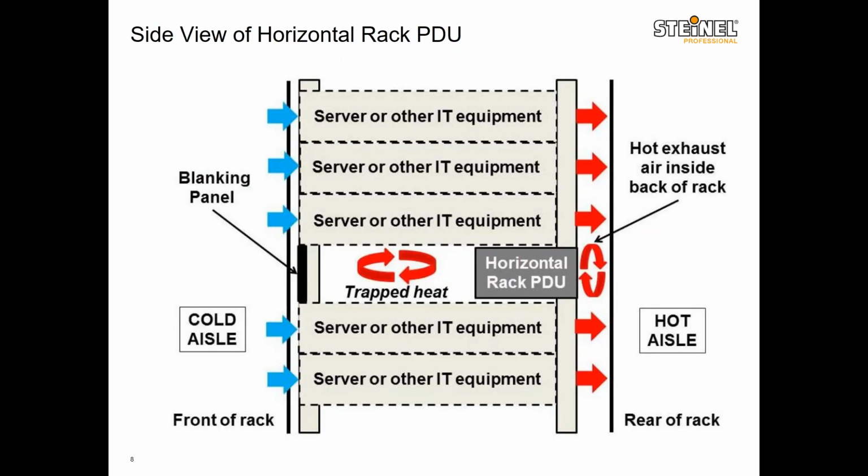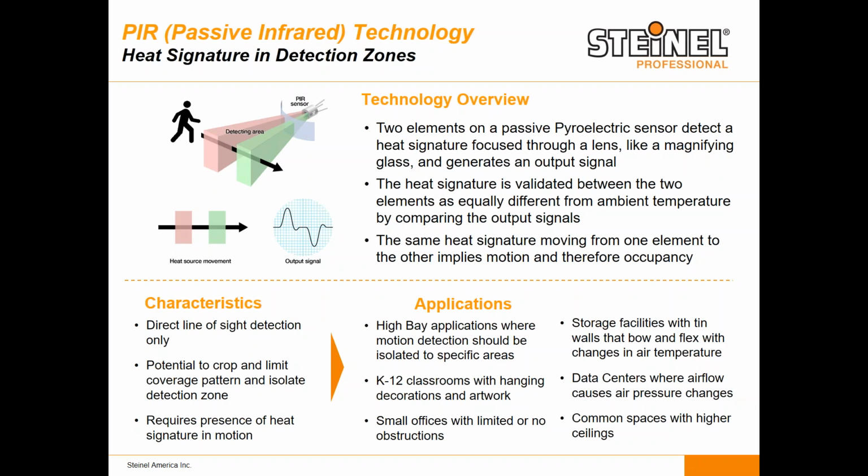Again, I won't go into this because Priya already explained it, but an infrared sensor is the best solution here, because an ultrasonic sensor projects a sound wave into the space. Well, sound uses air as its medium to transmit through the space. So you can't use an ultrasonic sensor in a space like this because of the massive amount of airflow. The medium of that sound wave is being distorted, and it'll always false trigger.